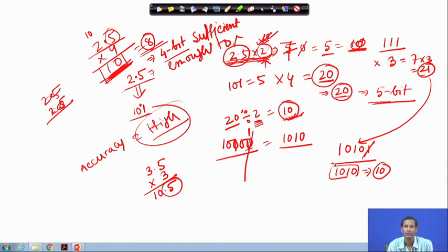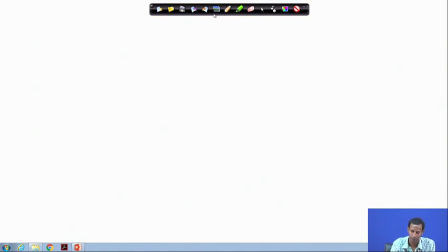If the result is even, like 20, and the 0 is discarded, there is no chance of accumulating any error. As this position is 1, meaning the number is odd, doing truncation means you are accumulating the quantization noise, the truncation error. So this is the example of scaling.